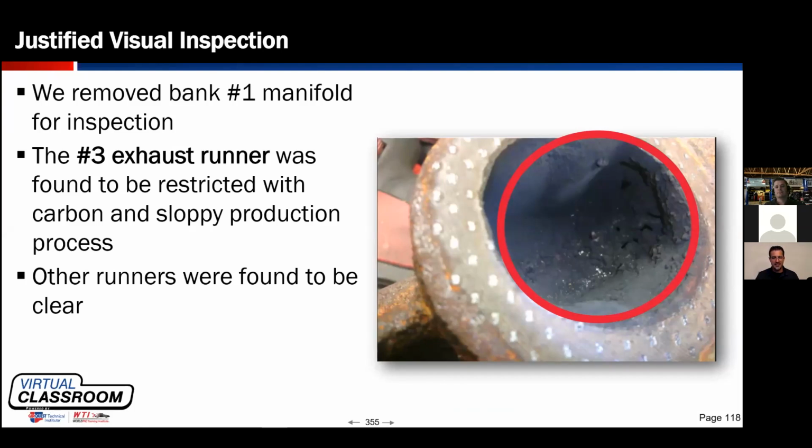It was the in-cylinder waveform that proved the cylinder could not exhale. It didn't say why. Not until he implemented his cursors and did some measuring. Logic told him it wasn't a camshaft because it only affected one cylinder. Logic also told him it wasn't a catalytic converter because it only affected one cylinder and not an entire bank.